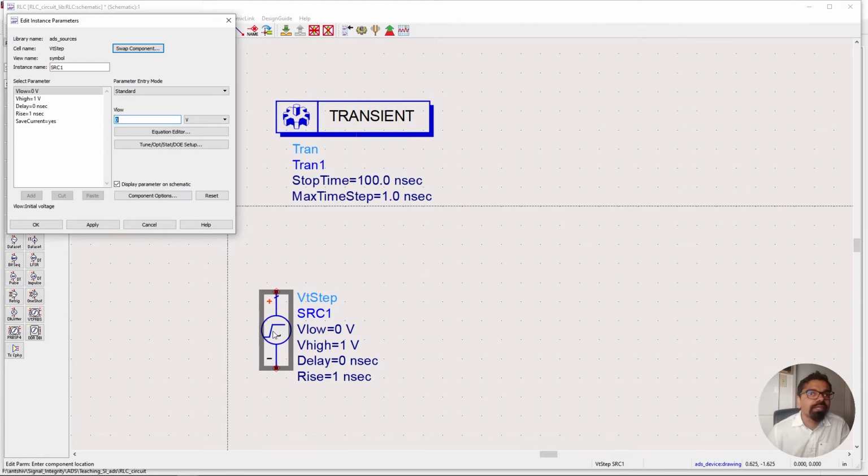When you double click on this, it'll give you different options as to how you want your rise to be. You could have this as nanoseconds, so you're basically putting this as 1 nanosecond. When do you want it to step response? What's your voltage high? And what's your VLOW?